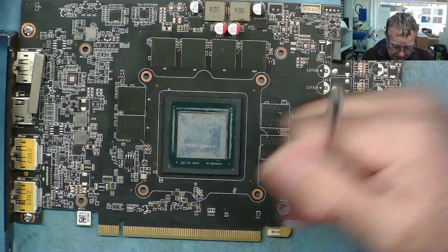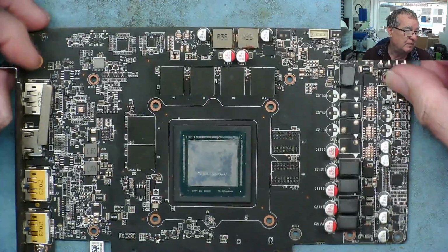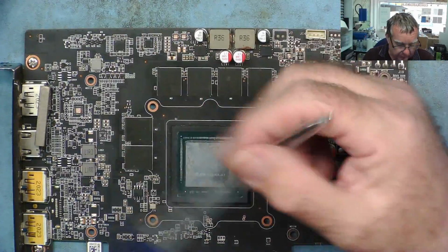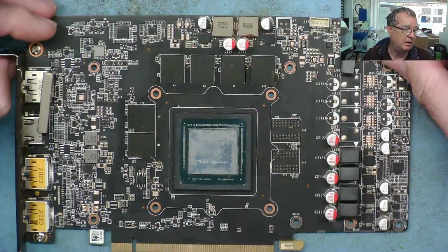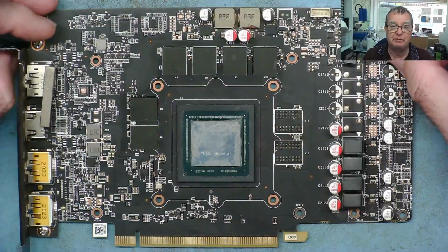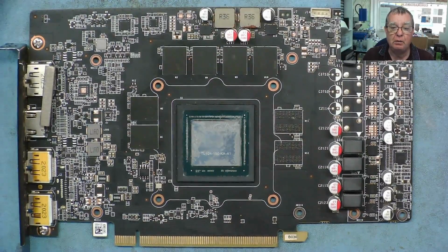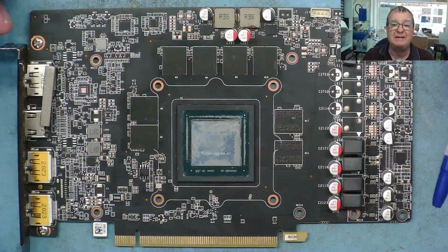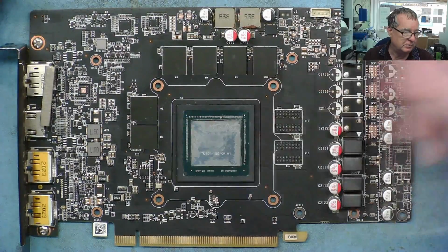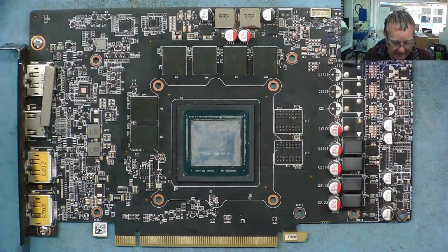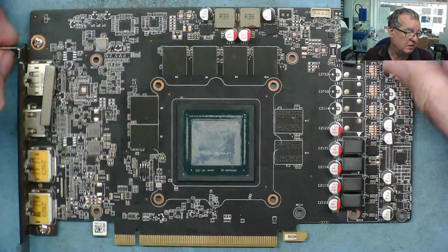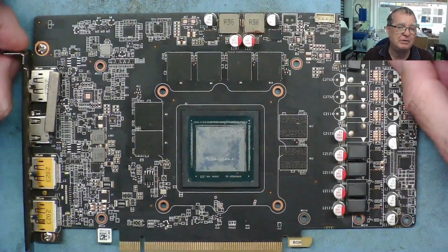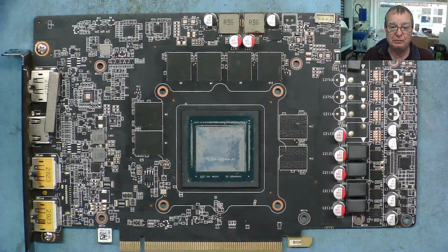To start with, this is a graphics card that has a short circuit high side MOSFET. I originally started to make a video with this. It belongs to a subscriber, and he thought it may have been put into a mining adapter the wrong way around. If you connect a mining adapter the wrong way, you're going to damage the GPU. I started to make the video and then realized this was an ideal opportunity to create this tutorial.